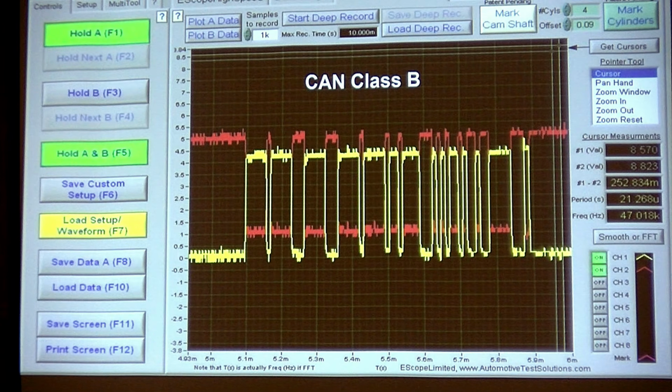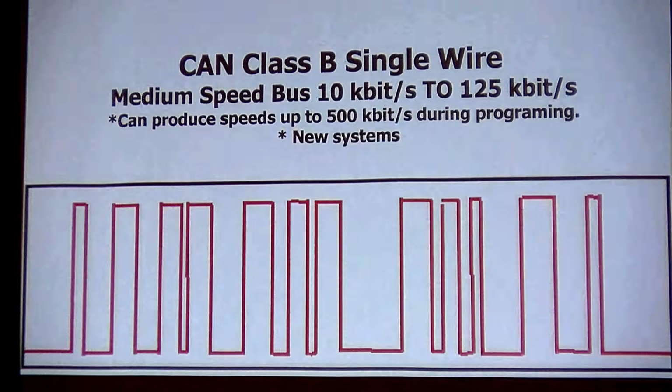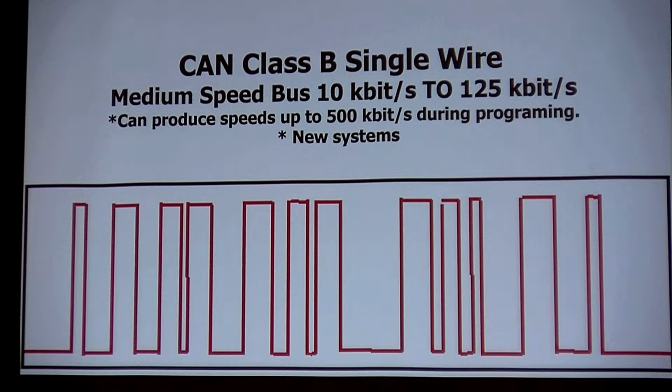Where do I use low-speed CAN? The DIM, seats, all these other types of structures that we have. This isn't going to be used for engines, transmissions, ABS, steering position sensors. This is a much slower bus. So you remember how we said that on these slower buses you don't expect a message back? That's because you would take up too much bandwidth. If you have to respond to every message that's coming in and you're expecting responses back and forth, you would tie all your bandwidth up.